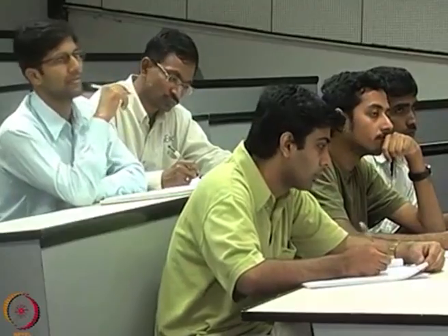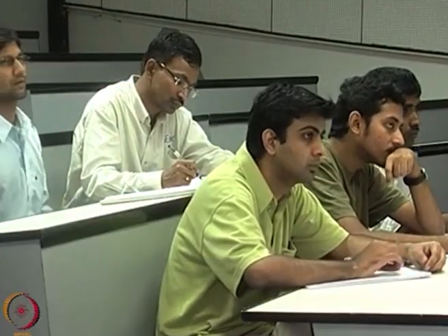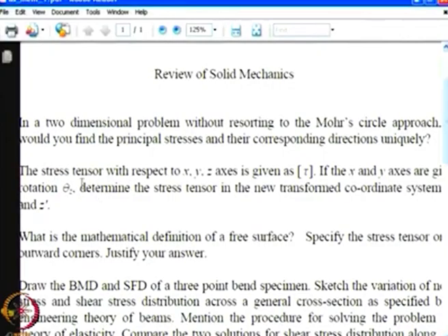And what we will now look at is the other question. The next question is: find out the stress tensor in a transformed coordinate system. In fact, the whole of strain gauge analysis, if you know the tensor transformation law, you can comfortably understand. Stress is a tensor of rank 2, strain is also a tensor of rank 2. So, the second question essentially asks you to recapitulate your understanding of the transformation laws. So, once you know the transformation law, the whole of strain gauges you can handle.